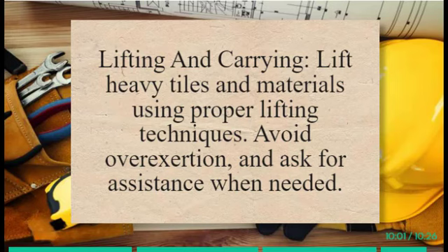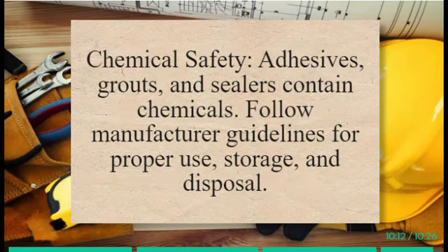Lifting and carrying. Lift heavy tiles and materials using proper lifting techniques. Avoid overexertion, and ask for assistance when needed. Chemical safety. Adhesives, grouts, and sealers contain chemicals. Follow manufacturer guidelines for proper use, storage, and disposal.